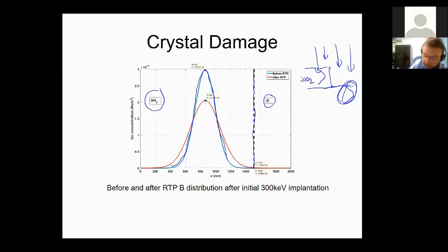If we put it into the annealing process but do not strip the silicon dioxide away, the Gaussian distribution of the ions will also diffuse. So instead of staying confined, the concentration will relax and propagate.